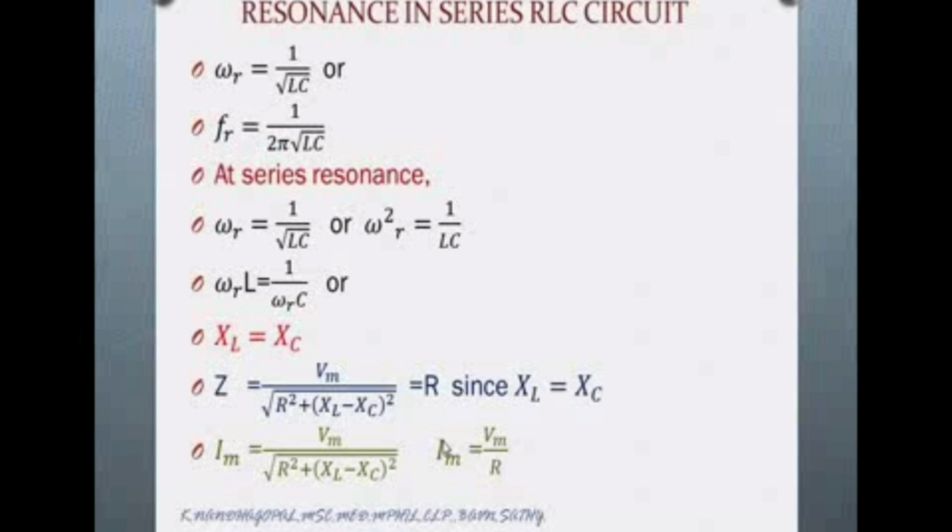Resistance decreases, flow of current increases. Here current is reciprocal to the resistance. When the current increases to maximum and resistance becomes minimum, it is used in the application of the series RLC resonance circuit. So the application is that it is used in TV and radio tuning circuits. So it is used to tune the different frequencies. The tuning is commonly achieved by varying the capacitance.